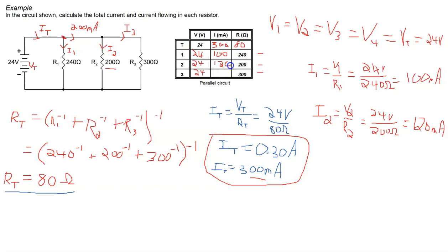And so let's think about what that tells us. If I got 200 milliamps coming this way in the circuit and I2 was 120, I already know the value of I3, right? It will be 80 milliamps if the math is correct. So I can use Kirchhoff's current law to find that. Okay, 80 milliamps. Now we can write Kirchhoff's current law as, the current here, which call it IA, let's say, is equal to the sum I2 plus I3, and figure out I3 from that.